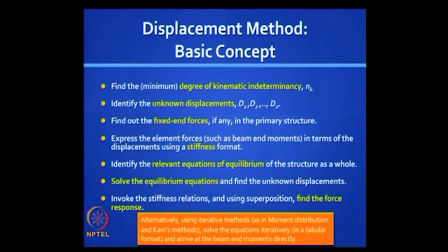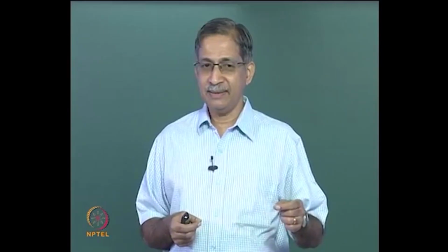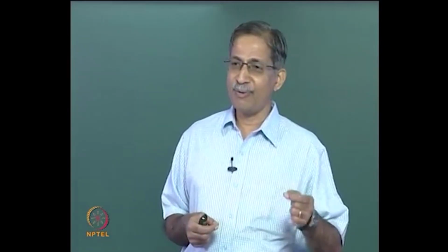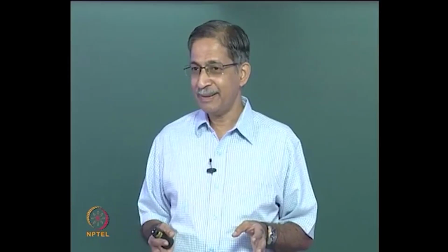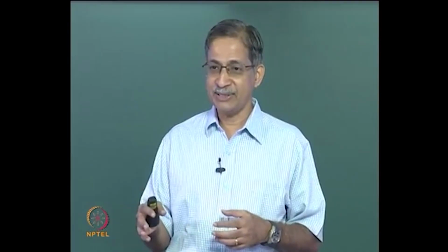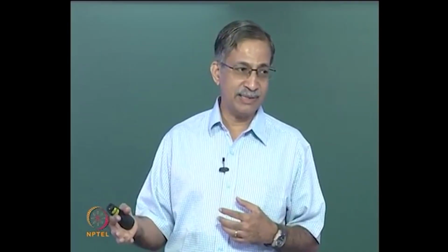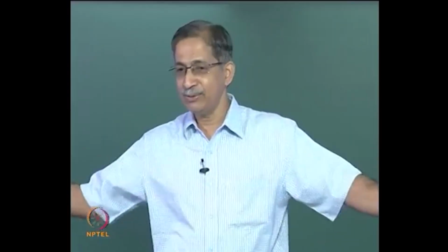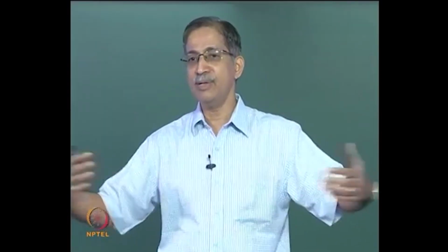So the moment distribution method and Cross's method, unlike the slope deflection method, which we will study shortly, give you the moments directly. In fact, there is a question that is often asked: is moment distribution method a force method because you get the moments directly, you do not need to find any unknown rotations or displacements? That is because you bypass the step of explicitly finding the rotations and invoking the stiffness relations, and just distribute the moment directly to the component beam elements.